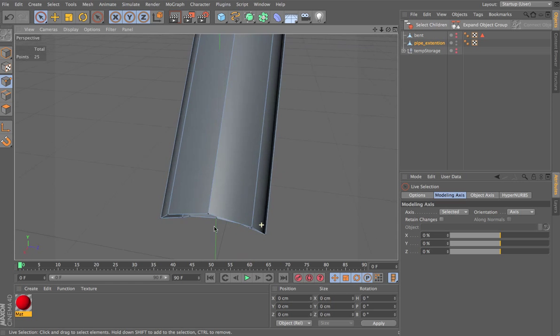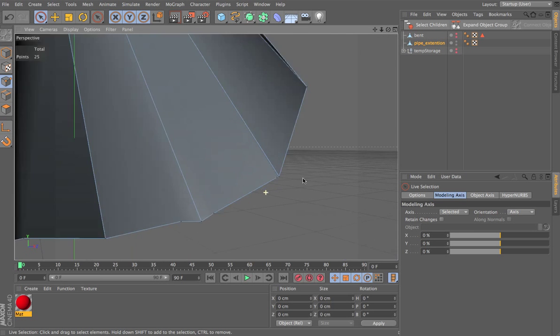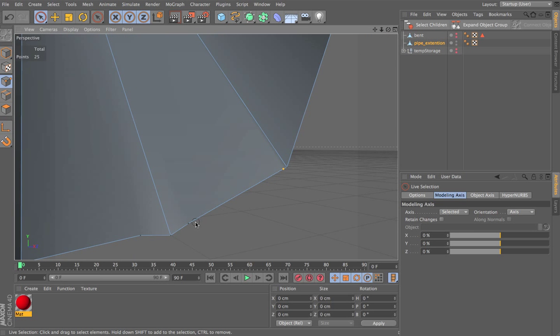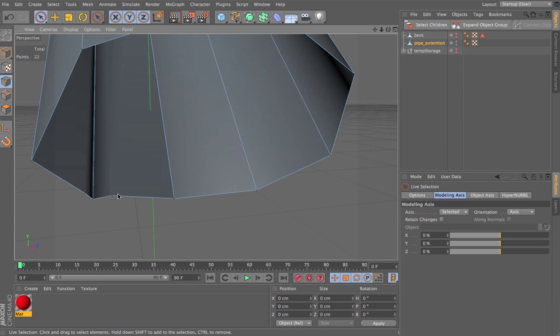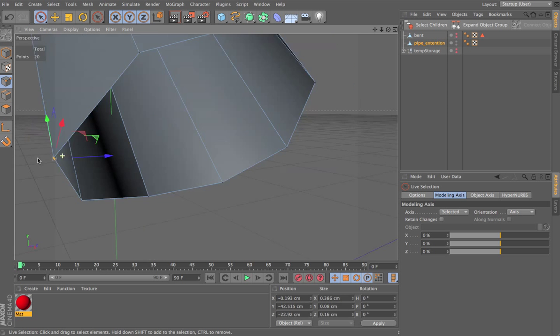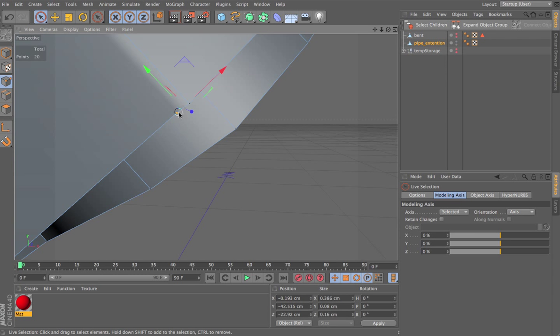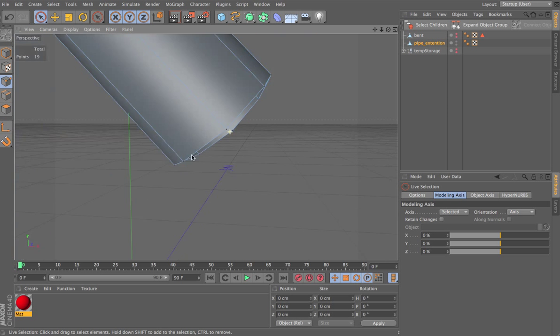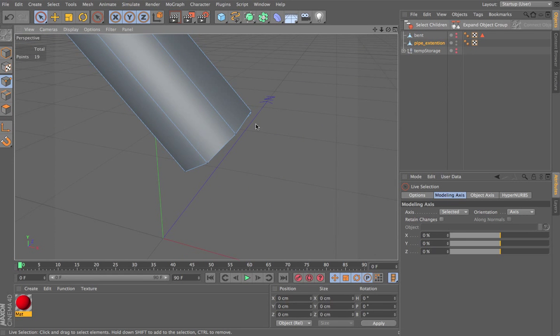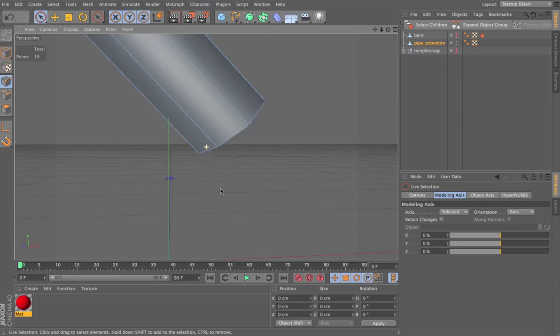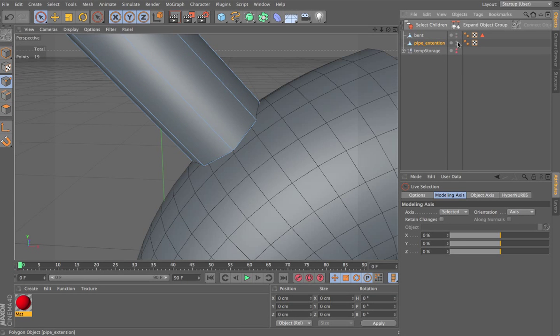Probably another modeling technique can take care of this automatically, but I'm just showing you the raw basics of modeling this way using Booleans. Okay, small cleanup. I mean, the 30 seconds or less it's going to take me to clean up, I've already saved by having parametric objects and controlling how the object looks a bit better. So there we go.